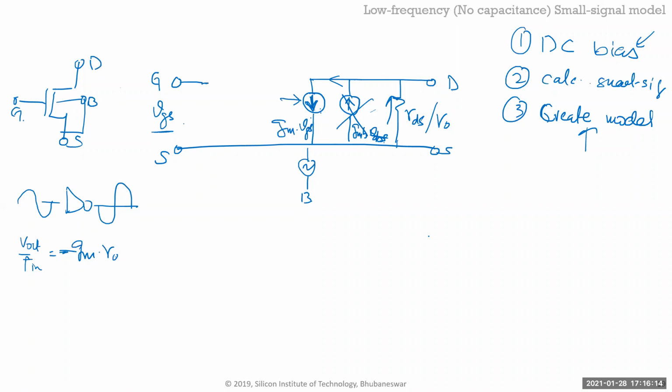Okay, so GMB is in phase, in the same direction as VGS or VBS, but the GM1 is inverted. Okay, so remember that in small signal, the current direction doesn't mean that some electrons are flowing in that direction. It's because you're looking at change of current, right? So this VD is just showing the change of current. So all it means is that if I have a delta V increasing in one fashion, the output will be decreasing. If it is in phase, then I would show the current in this direction. Okay, so that's the important thing.